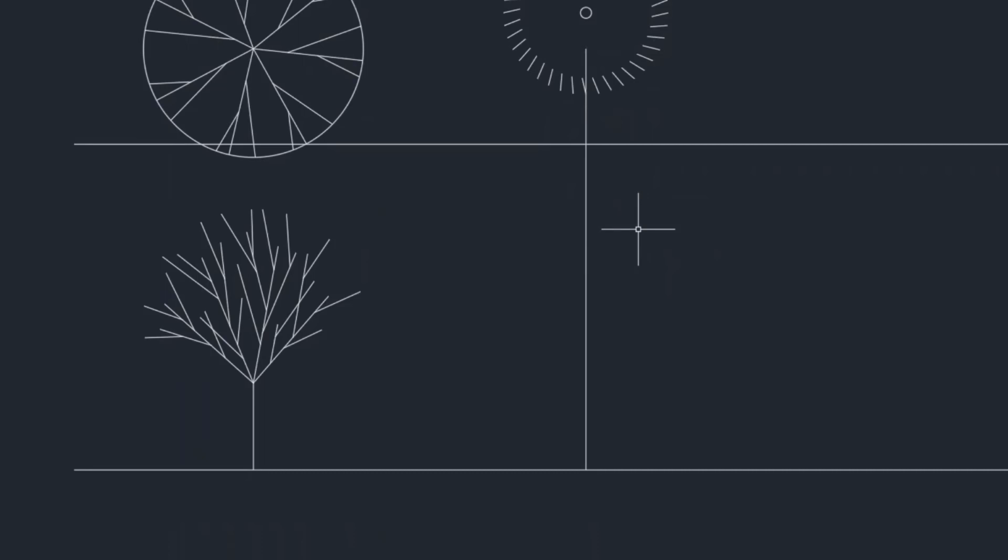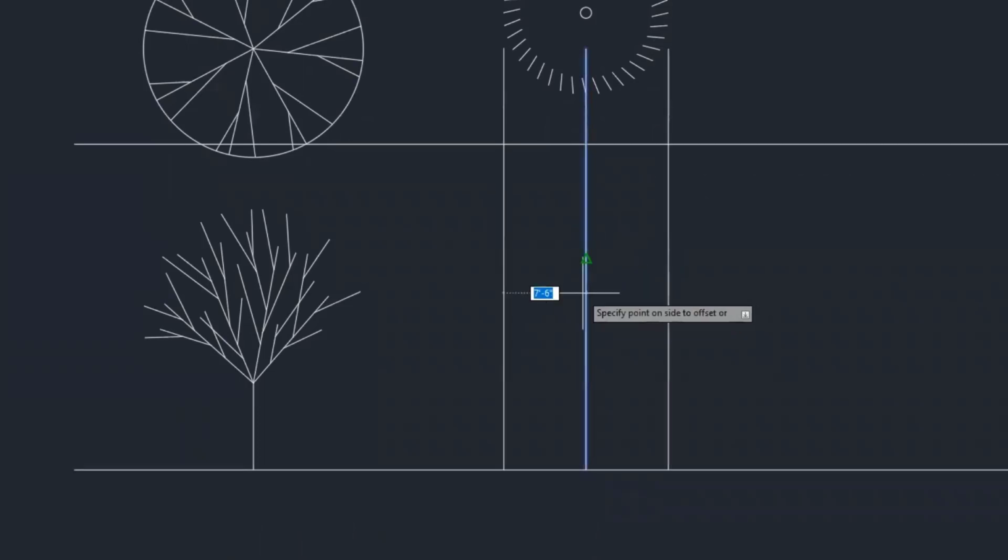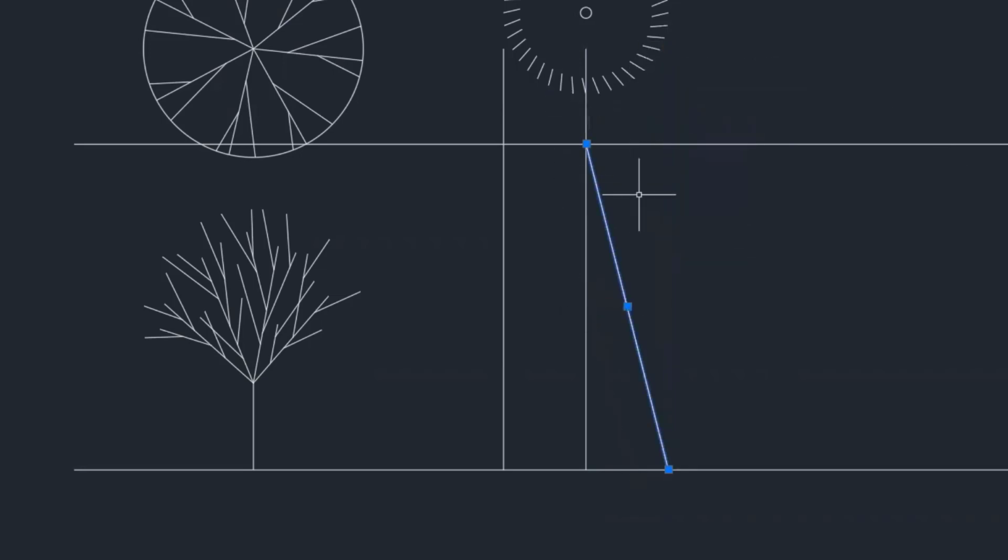Half of 15 feet is 7.5 feet. One way to do it is to offset. So I offset a distance of 7.5 feet and enter. And I offset this line out that way. I offset this line out this way and enter. And then I can take my grips and grip it and bring it right here. That takes care of that one. Tap the escape key, use my grips, grip it here and stretch it there. So that's one way to do it.